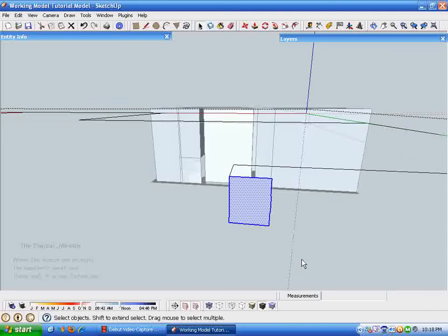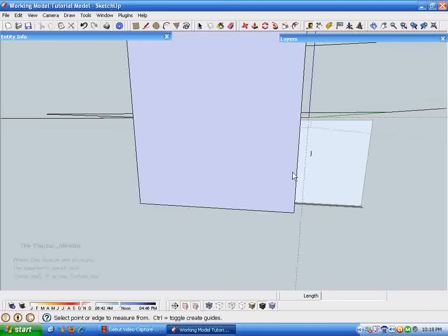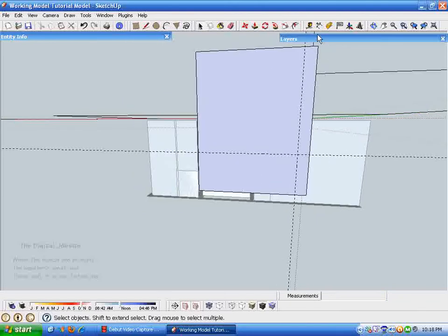offset or projection. But I'll just create a quick crown molding here, kind of a standard profile. I'm going to go out 1/4 and up 3/4, and then we'll just take the arc tool. Just going to draw a little radius in here. That should do.